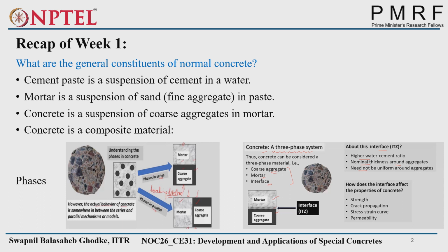Normal concrete also has a little bit higher content. But the thing is that in normal concrete and high strength concrete, high strength concrete will have a lower water to cement ratio. If you want to classify it according to the water cement ratio, it will have the lower water to cement ratio. And if you want to classify it according to the failure pattern, if you go with the